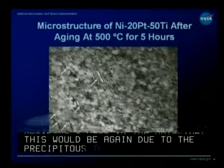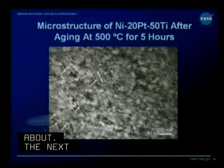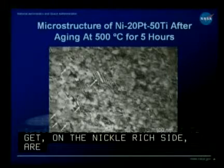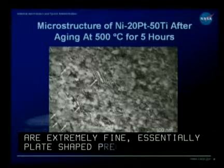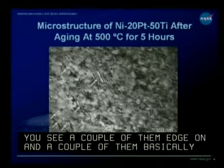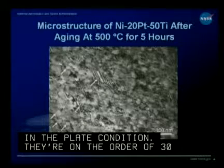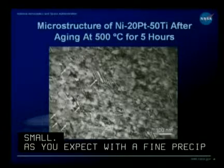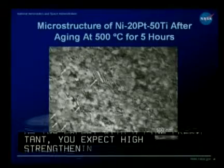These very fine precipitates that you get very close to stoichiometry, but on the nickel-rich side, are extremely fine, essentially plate-shaped precipitates. You can see a couple of them edge on and a couple of them basically in the plate condition. They're on the order of 30 nanometers in size. They're extremely small. And as you would expect, with a very fine precipitate, you would expect a very high strengthening in the materials. And that's actually the case that you see in the next slide.